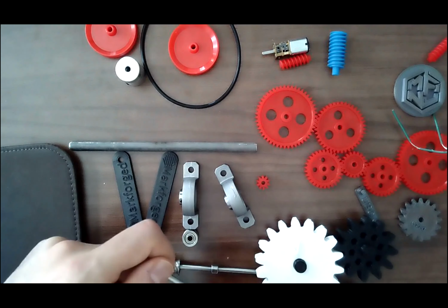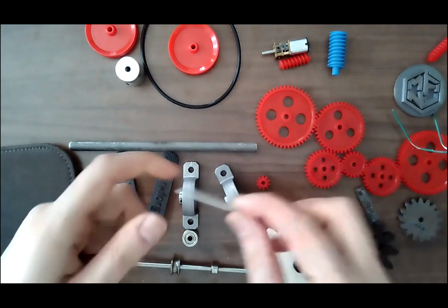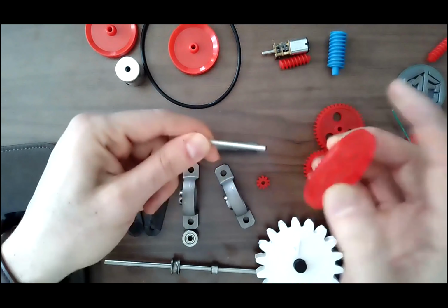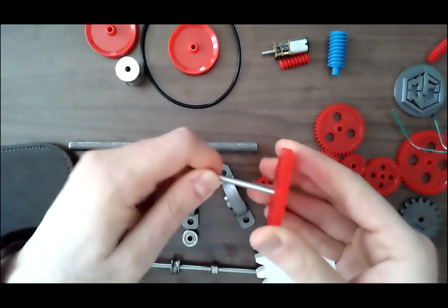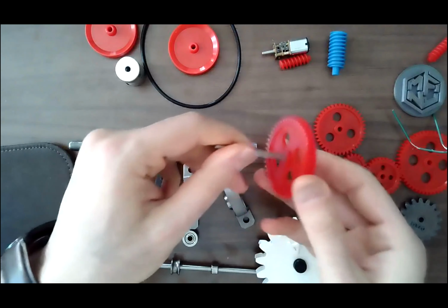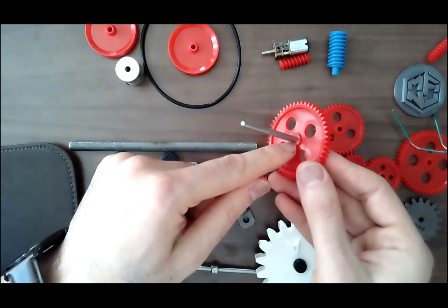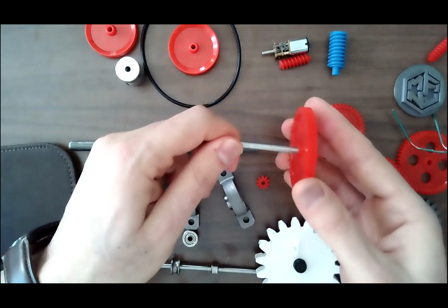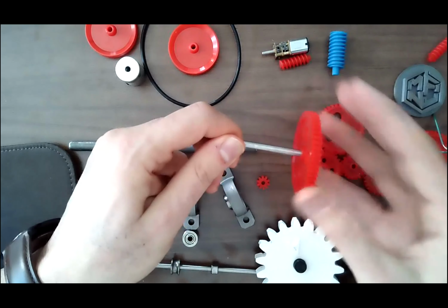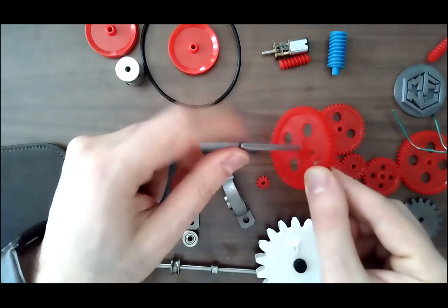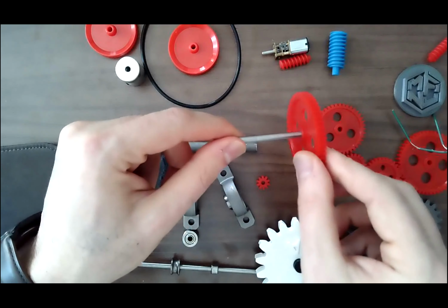And of course, when we talk about a shaft and a gear, the gear is going to be a tight fit to the shaft. In this scenario, I can glue them, but in industry, they are going to be press fit. And sometimes people use brackets or welding to fix the gear to the shaft.